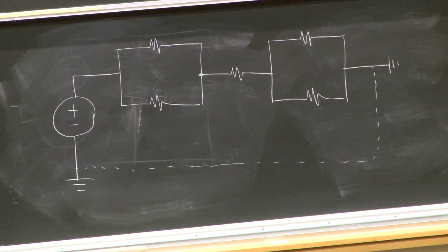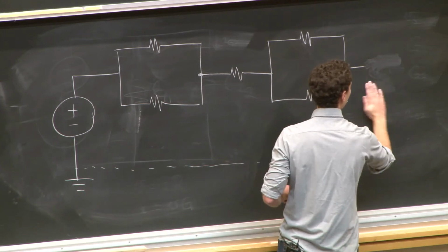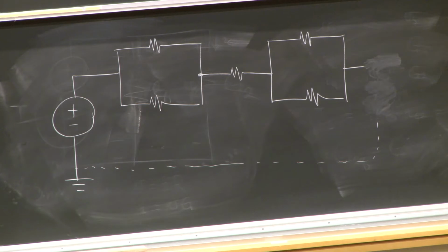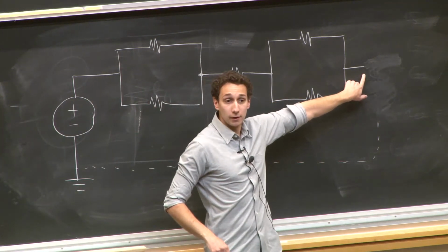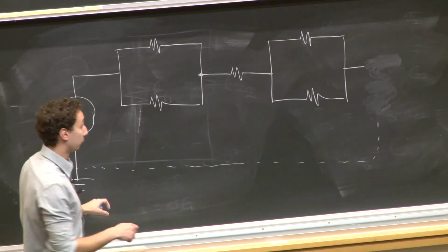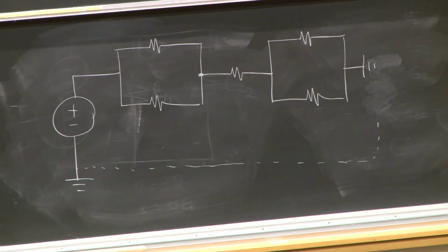What happens if they're not connected? Then you have issues. In a real circuit, you wouldn't have a return path. Let's think about KCL for a second. Let's say I didn't ground that node. This is a good question, by the way. Would there be any current in my circuit? No, right? Because if we look at this node over here, there cannot be any current. Great question. So we have to create a return path for our current.